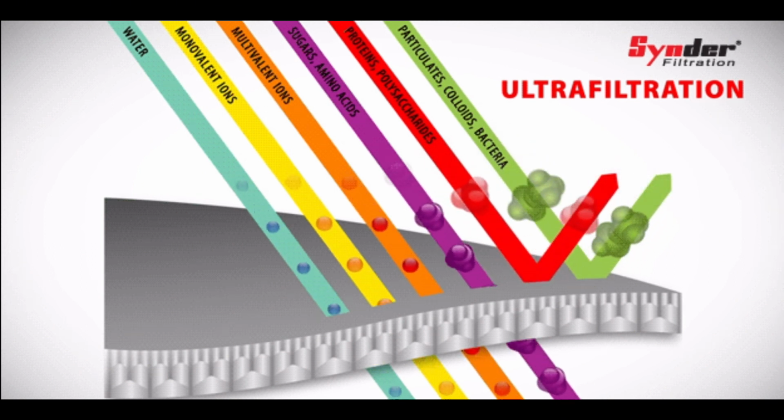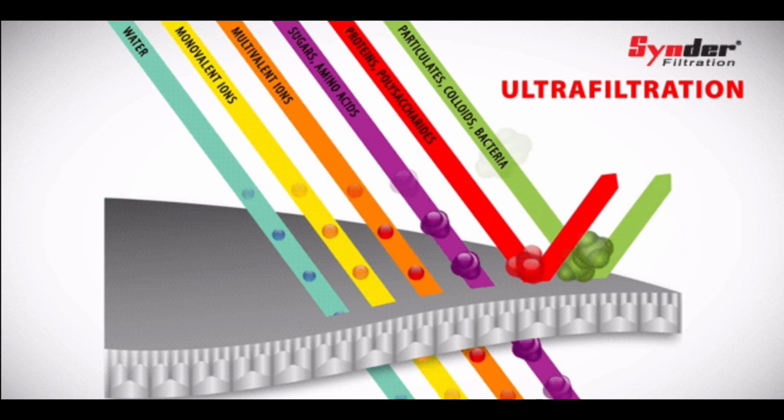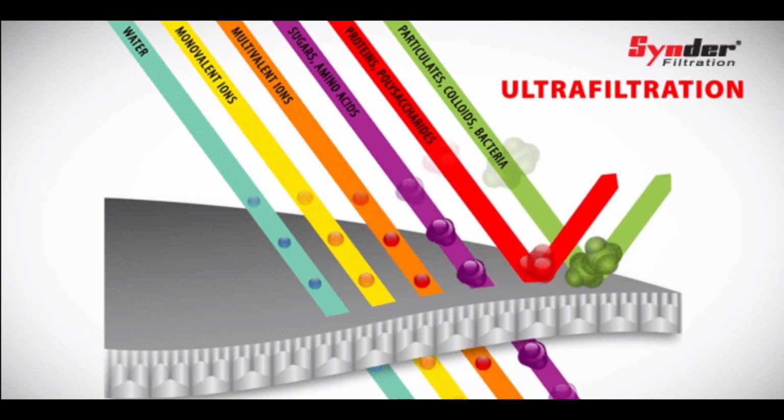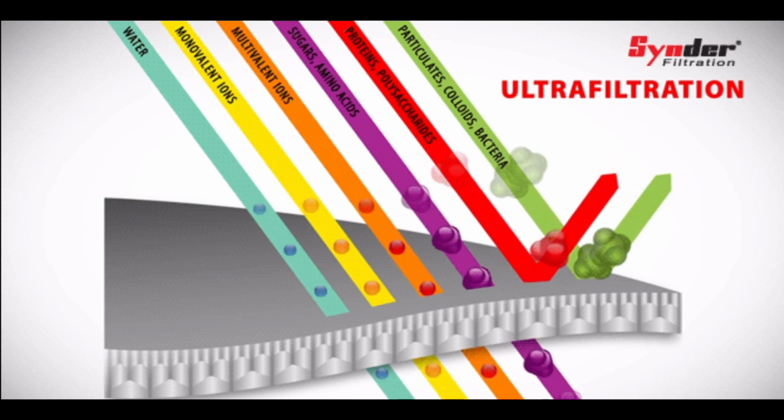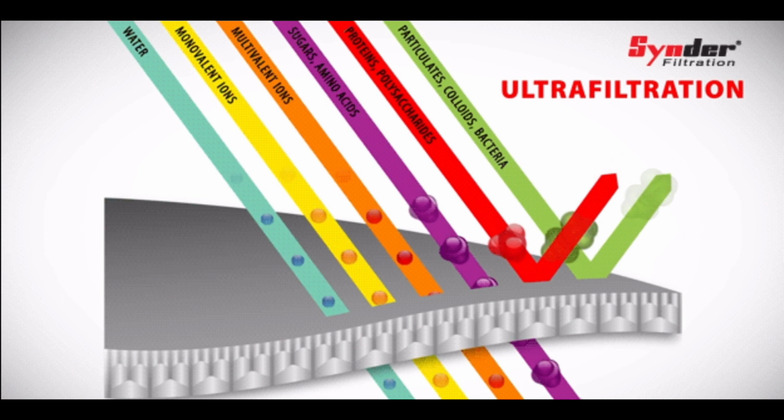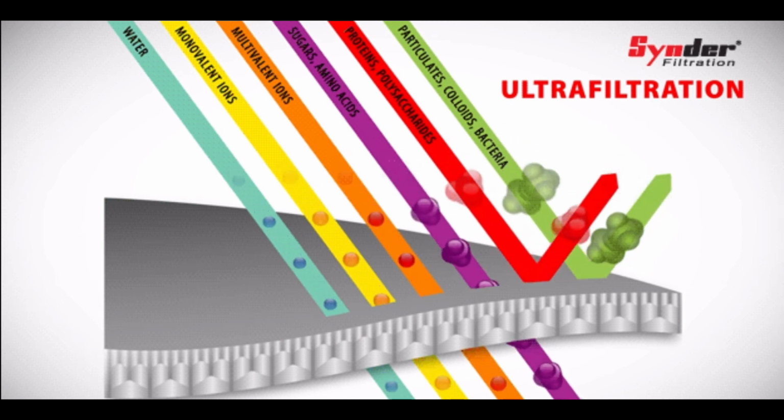So, from the three processes that I have stated, what do those three remove? For the ultrafiltration, it removes bacteria, protozoa, and some viruses from the water, while nanofiltration removes these microbes as well as most natural organic matter and some natural minerals, especially divalent ions, which cause hard water.